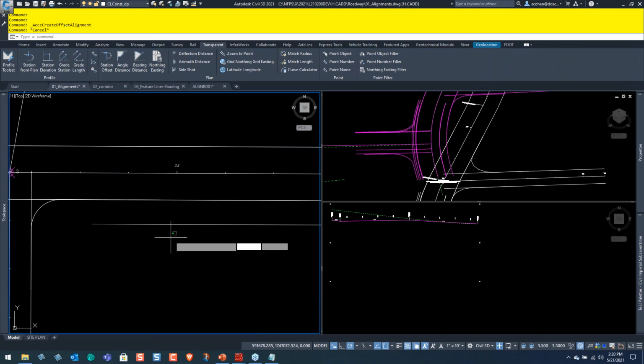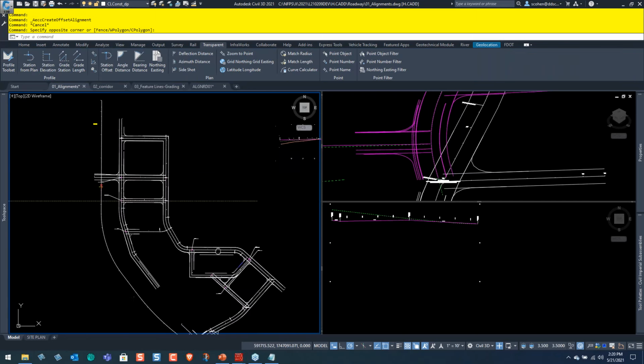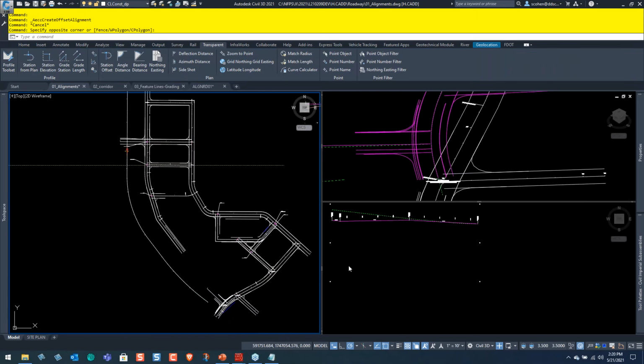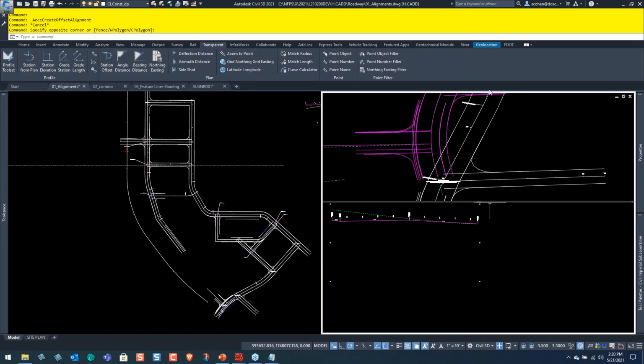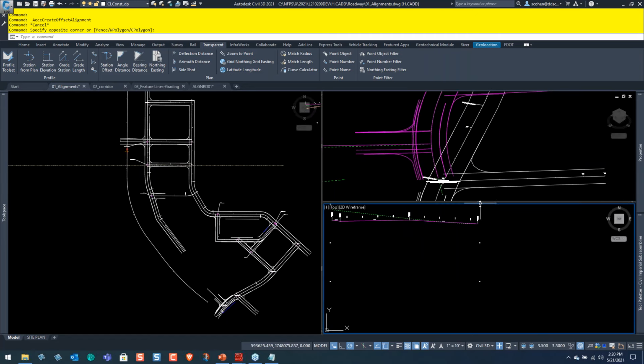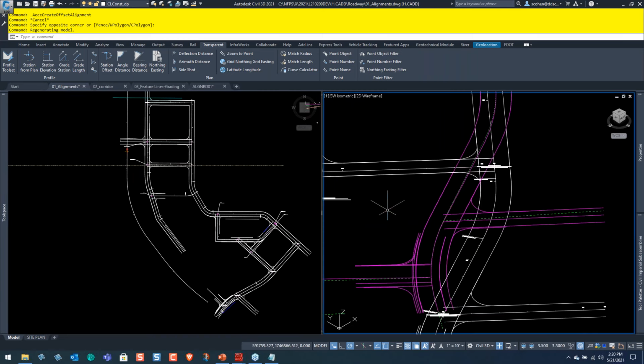Okay, one of the other tricks I will just show you, just for time constraints, I want to make sure I get to all my tips here. Let me get rid of this viewport. Again, the way to do this is just simply drag up here and then hover at the top and let go. Oh, let's do it again. There we go. Now I've got back to my 2 viewports. Okay, let's just change this back to top by clicking the view cube there.